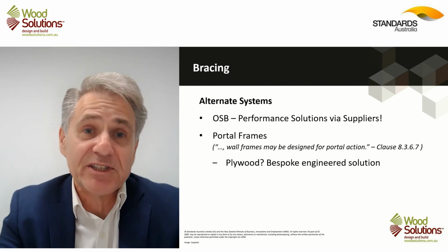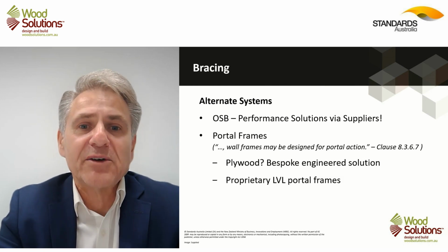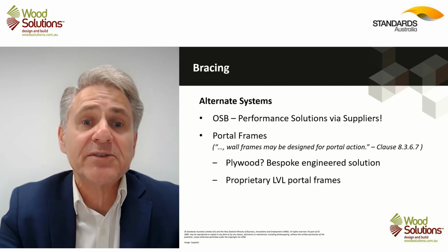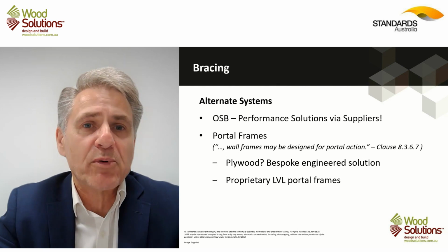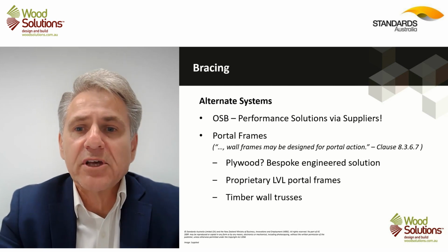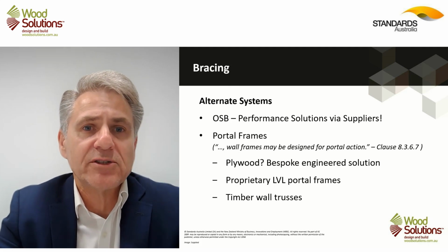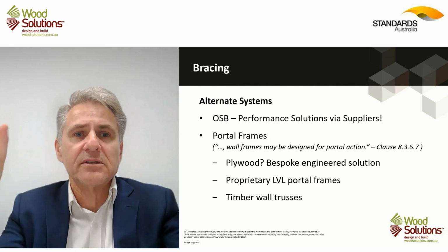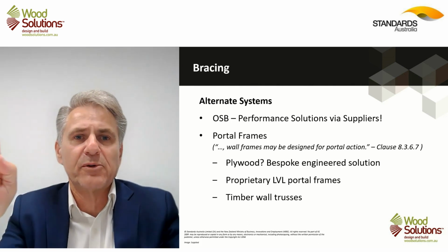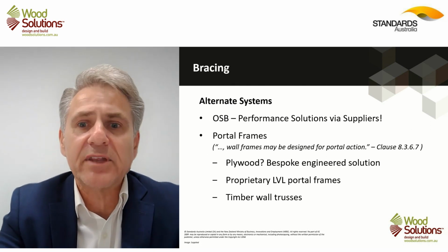I suppose each of these are engineered designs. There are proprietary LVL portal frame systems, and there are also truss type wall frame systems that can be designed. So we can have larger openings, with these portal systems around the opening that can provide that lateral restraint to the end of that wall.